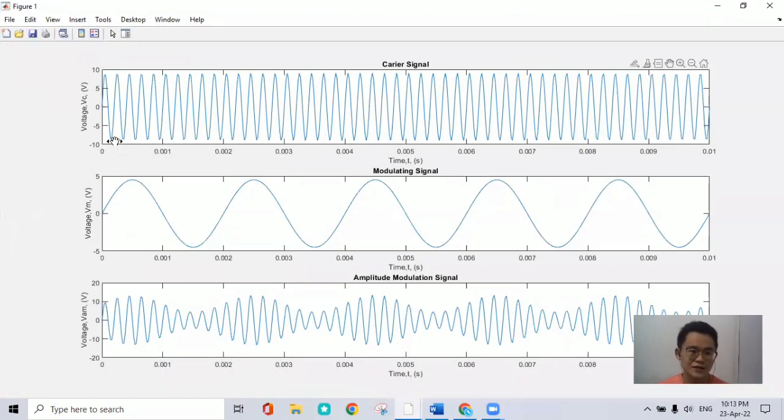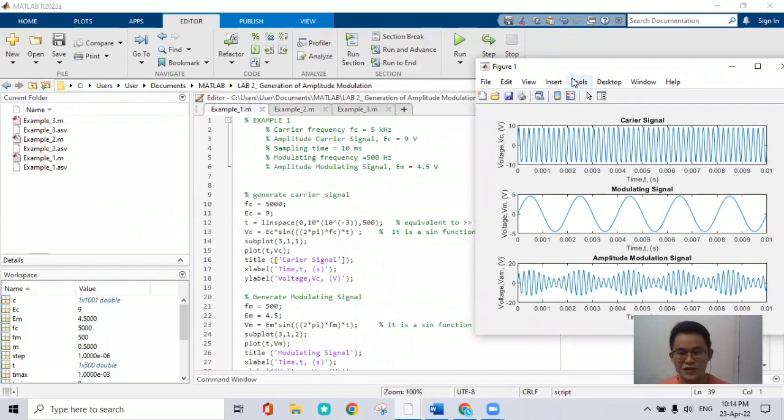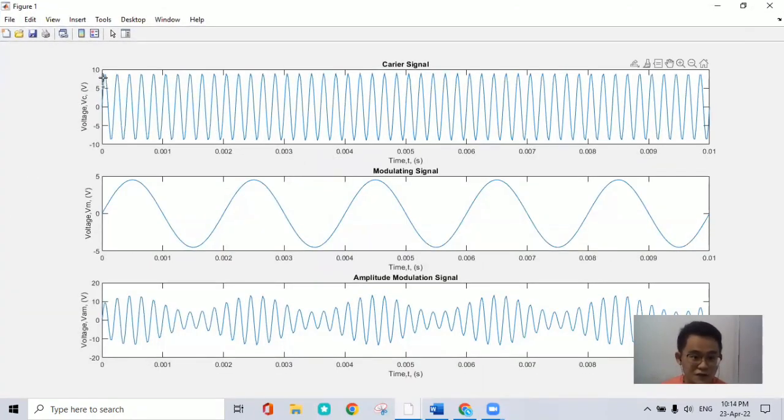So as we can see, this is the graph generated by MATLAB. I can show you that this 500 here is telling us we will have 500 data points in this graph. You can see the dots, right? So this means from 0 to 0.01, I will have 500 data points. If I replace the 500 with any number such as 200, our curve will not be so smooth. So the larger the number, the smoother the graph is, and the larger the number of data points.